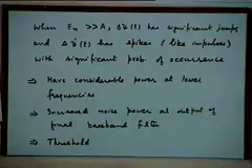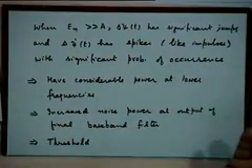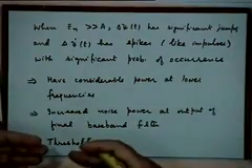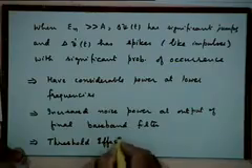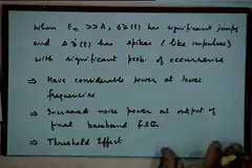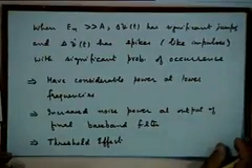So your analysis earlier did not take into account these spikes, because these spikes did not occur or occur with very, very low frequency, very, very low probability. But this new analysis will have to take this into account, this analysis which is for the case of high noise. Okay, so this leads to the threshold effect. Okay, so there is a more precise mathematical analysis that one can do, and one can work out a precise expression for the output SNR in the threshold region. But since I have not gone through the mathematics of it, the expression I like you to look at in the book itself. There is no point just writing the expression here.